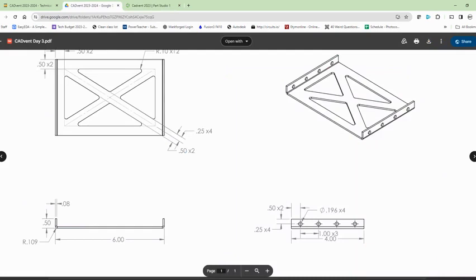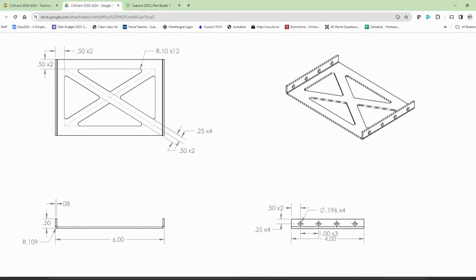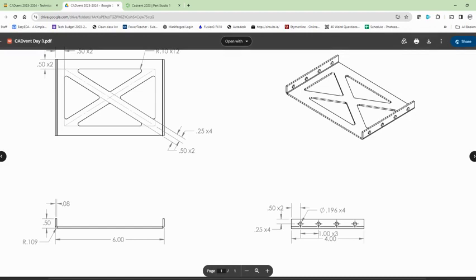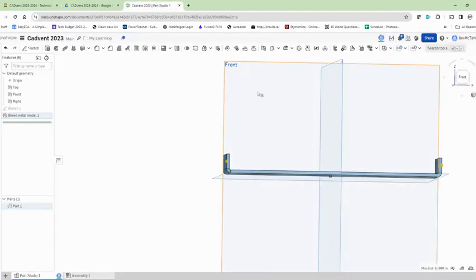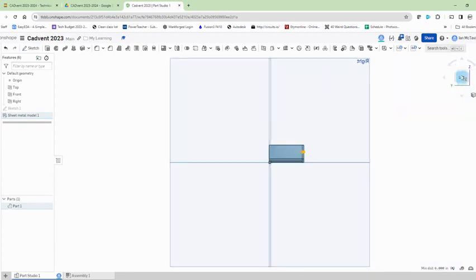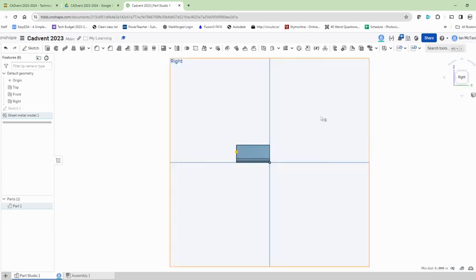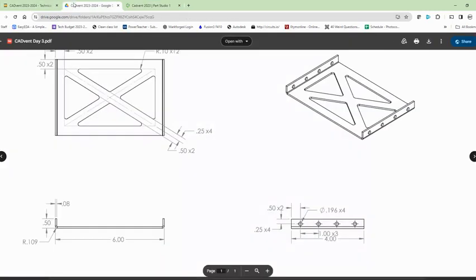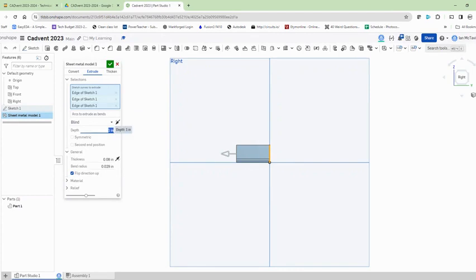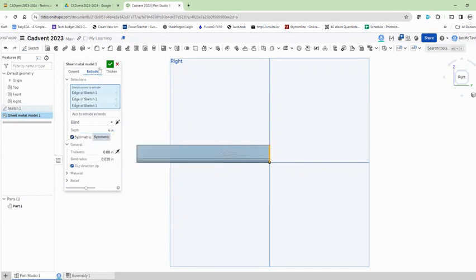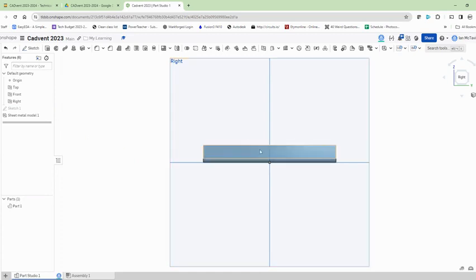Now, on the side here, I can see the holes. And again, if this is my perspective drawing, there's my top, there's my front. So that's my right-hand side. I like to just keep that in mind in case something's not symmetrical. So I'm going to use the right side. Now, the one thing with my sheet metal model, this is supposed to be 4 inches, so I extruded that 4 inches, and I am going to make it symmetric so that way everything's centered properly.